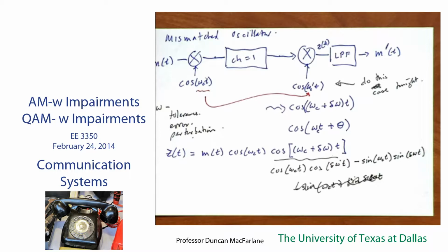When you do a lab, you usually do an error analysis, right? So if you design for a resistor of 100 ohms, and you have a 5% tolerance, that means you've got to run your circuit with 95 ohms to up to 105 ohms, and that's the range. You see how your circuit behaves across that.